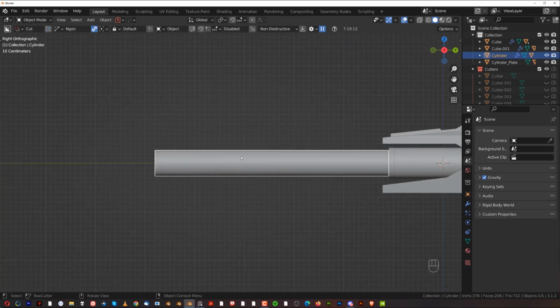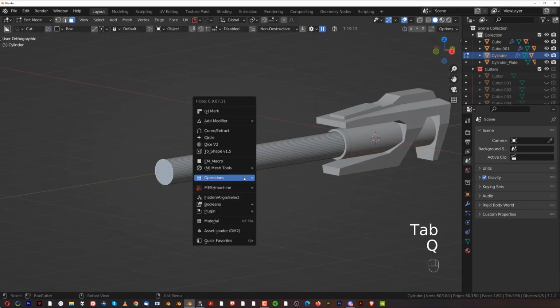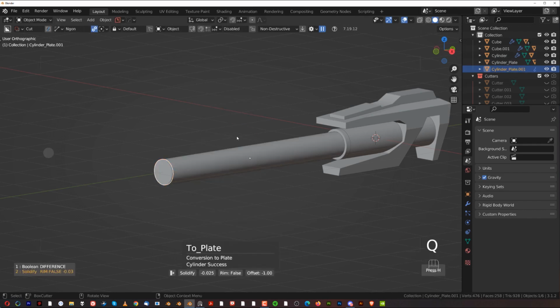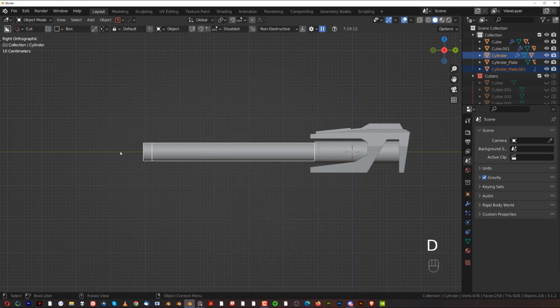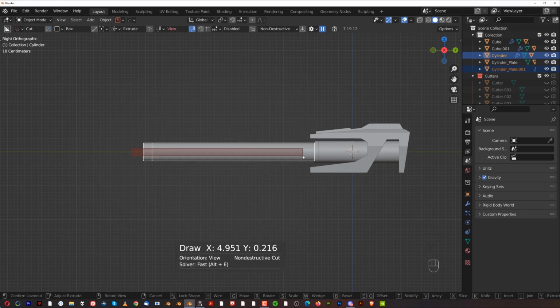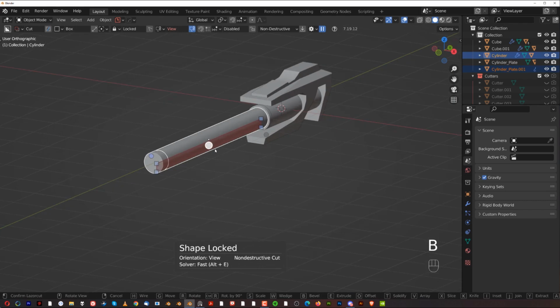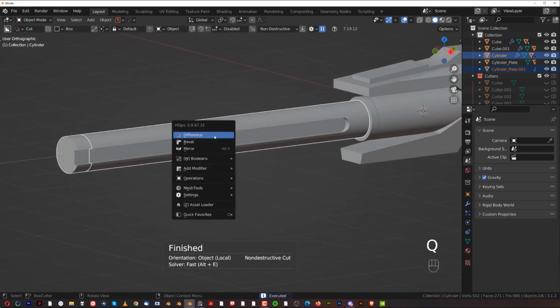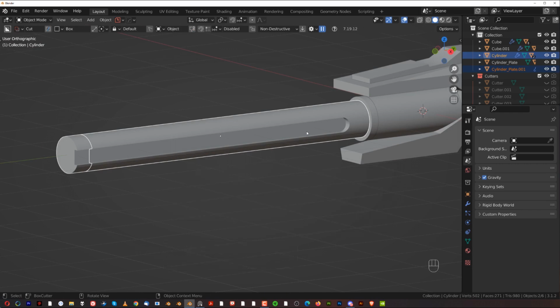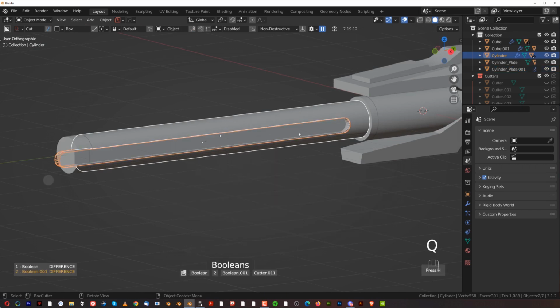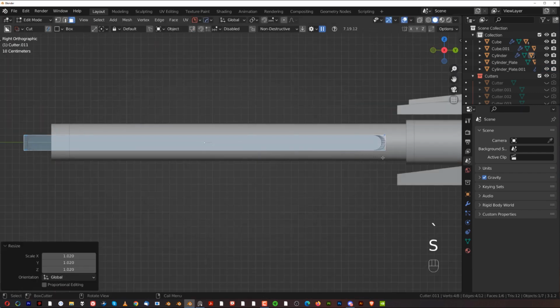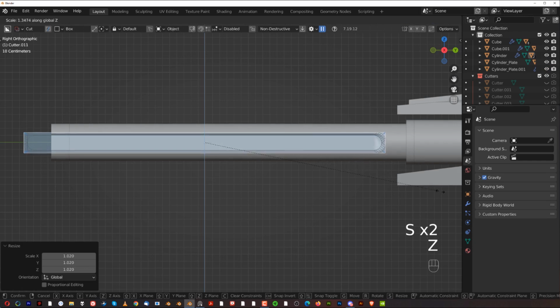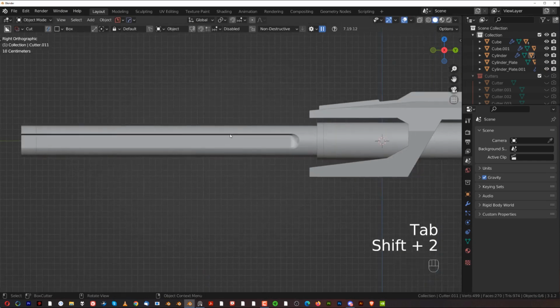That's cool. Here on the front, we could have another element, and select them both, and we could cut it here from the side like this. Press B for bevel and cut it through. And in fact, what we could do is let's just recover that for a second. So have a scroll and select the face here and scale this, and scale this on Z, so it kind of chamfers out. That's pretty interesting.